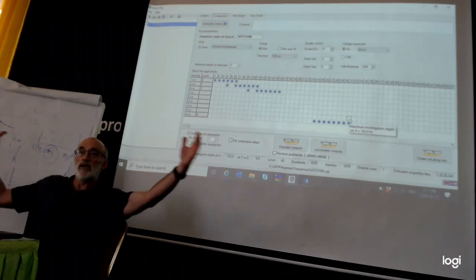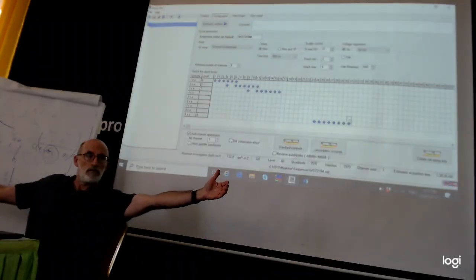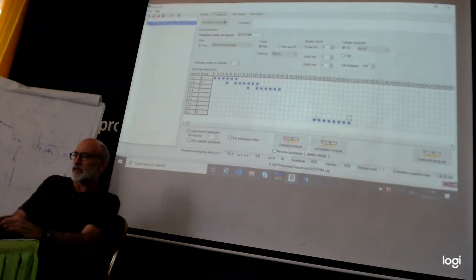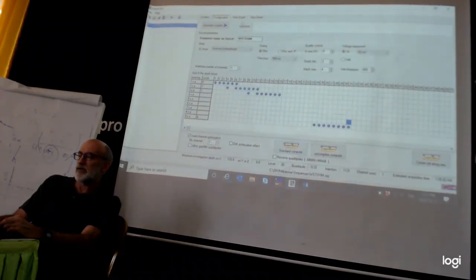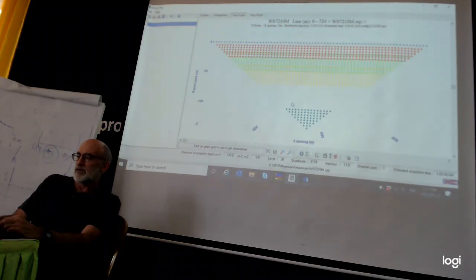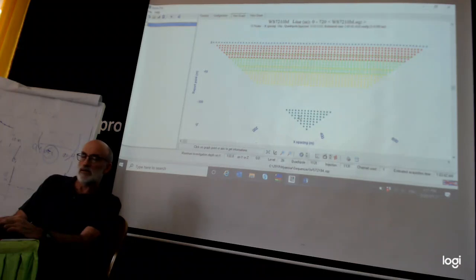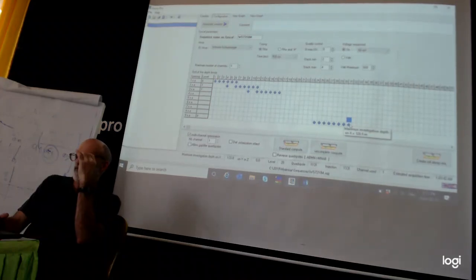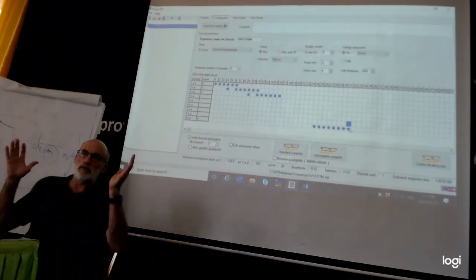Yeah, so 9A means your injection electrodes are 90 meters apart. So let's just see, to make this apparent, what 9A is giving you there. If we go back here and we check, that maximum depth is 128.5, but this will give you higher potential voltages.